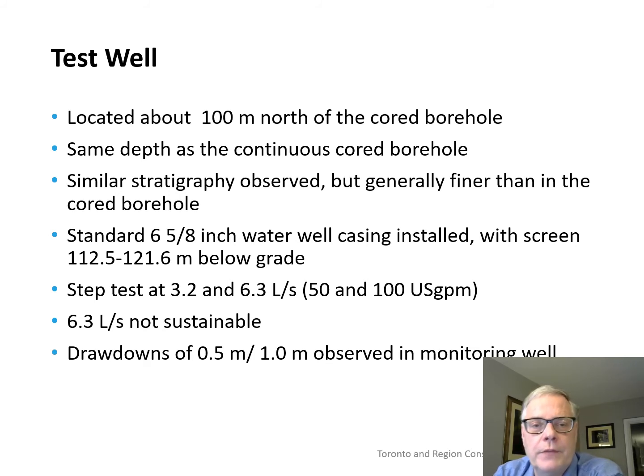And therefore we went in with a water well contractor about 100 meters north of that detailed core hole and drilled down to about the same depth to the bedrock interface and found mostly similar stratigraphy, but unfortunately a little finer than in the cored borehole. And as you know, it doesn't take much of a change in grain size to drive your Ks much lower.